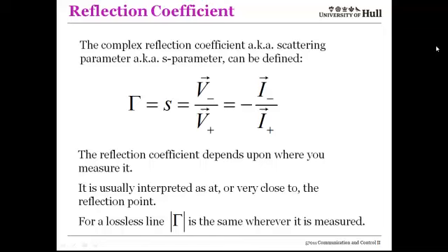There are some ratios we can define. We've already seen that the characteristic impedance is the ratio of the voltage to the current of the forward propagating wave. Wherever your transmission line goes through a sharp change of characteristic impedance, you'll get a point that reflects some power.